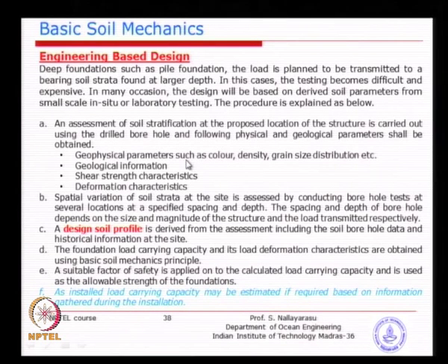Also, when they were trying to install piles in that vicinity, you could collect information from the old records. It will tell you whether it was hard driving or easy driving, whether the pile was going through easily. Then do a borehole at the site and collect information on the type of soil, strength characteristics either at the site or at the laboratory if you bring the soil back to the lab without disturbing it, and then its deformation characteristics like Young's modulus. I think that is very important.